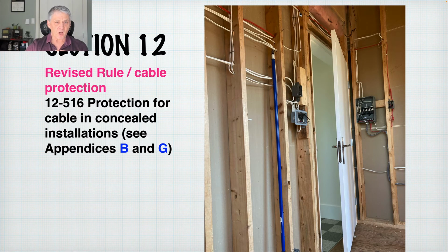This is where it'll not be okay. And they actually need a protection plate up there too. So this cable here is less than 1.25 inches away from this front edge. So they would have to put a protection plate all across here. Protection plates would have been required on the back side of this.